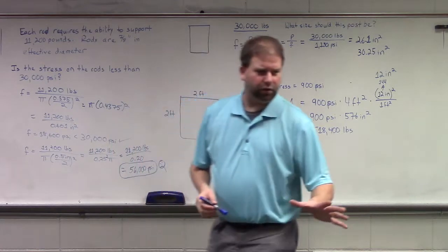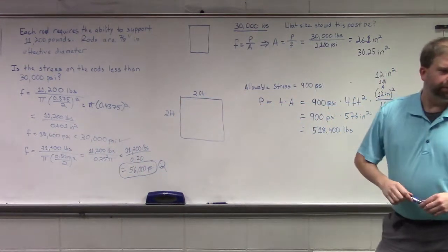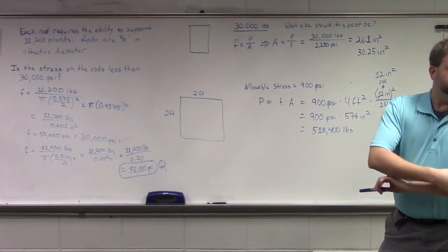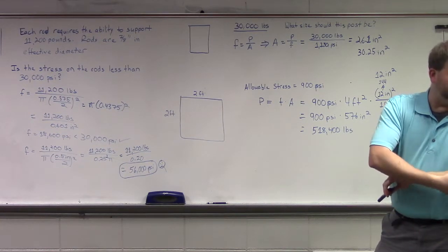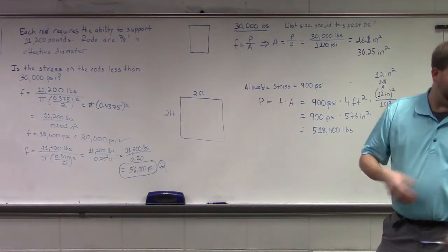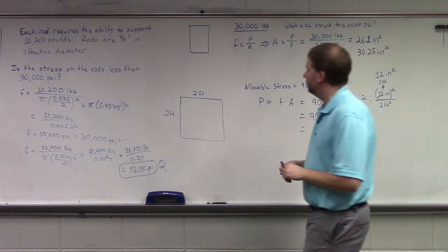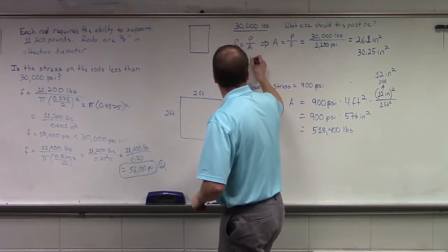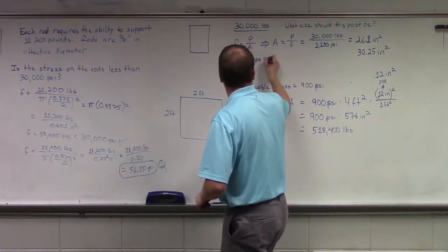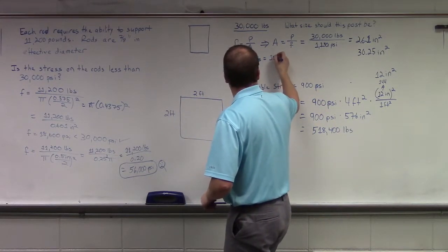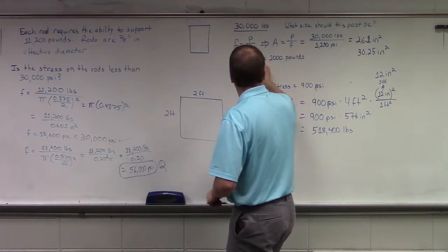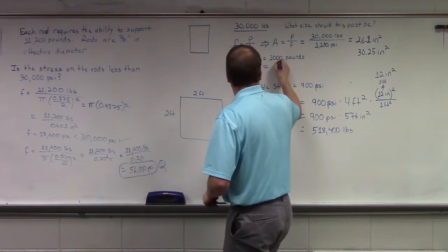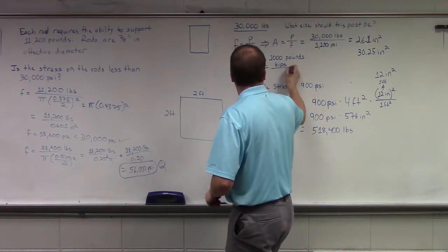So does that answer your question, Rush? Yeah, I kind of think so. The biggest thing that I was getting hung up with, because one's the kips and one's KSI, so I was like, well, how does that? So keep in mind, kips is 1,000 pounds, and KSI is kips per square inch. So it'd be KSI per kips. That's what's driving me nuts, is the label for it. So I'm getting for that problem in particular, it'd be 0.4 KSI per kips.